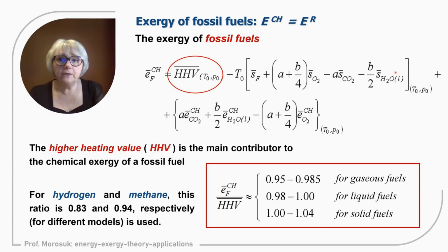And if we evaluate all these terms, we can find out that the main contributor to the chemical exergy of the fuel is the higher heating value. So chemical exergy mainly depends on higher heating value. If scientists are not familiar with the equation, or have no software, or would like to simplify the application of exergy analysis, there are very many publications where chemical exergy is associated only with higher heating value, and all other terms are neglected. There are even some recommendations for the ratio between higher heating value and chemical exergy of fuels.